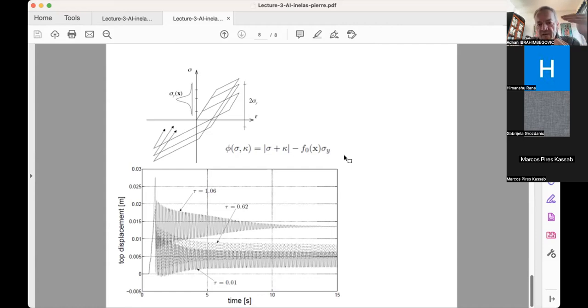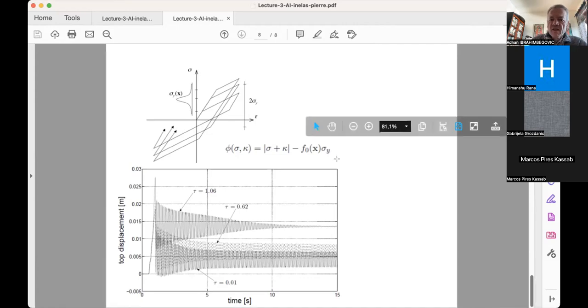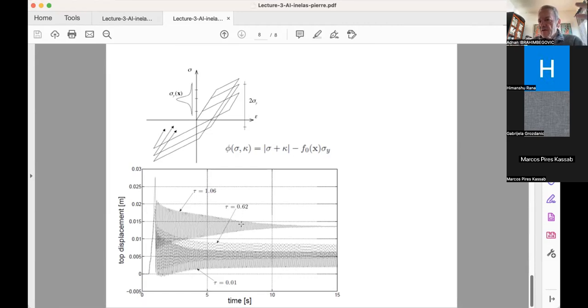And it turns out that once I have identification of a material parameter, plus I have quantification of the heterogeneity of my real structure, which is characterized here with the standard deviation or variability of the yield stress, the more it's heterogeneous, the more there's variability of the yield stress. You can start recovering something which looks like a proper decay, whatever the size of the structure. So you can hope that you are able to do the tests once and for all, and then extrapolate this to different structures as long as they're built of the same material.